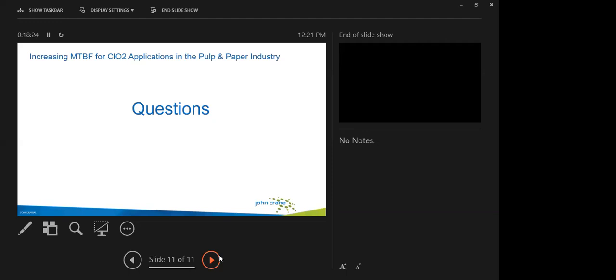Next question is, what is the max operating temperature? Again, it's 250 degrees F, but we have actually done some at higher temperatures. They have to be evaluated, and we would have to provide cooling to the seal itself, because you've got to remember, we have water as a barrier fluid. If the temperature due to heat soak is too high, we'll actually flash the water prematurely, and we won't get the liftoff of the seal faces. So the brochure will say 250. Anything above that will need to be evaluated.